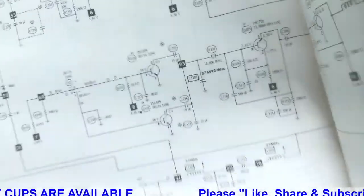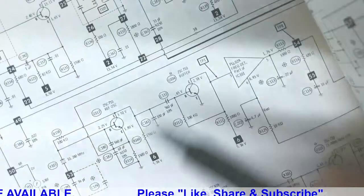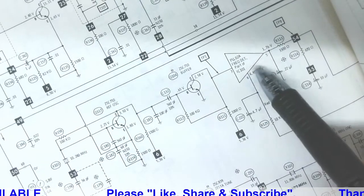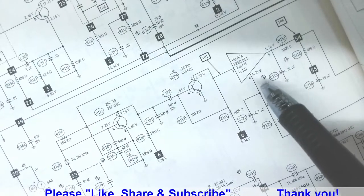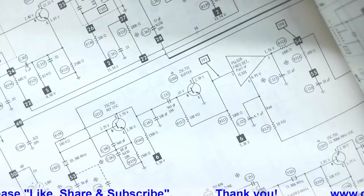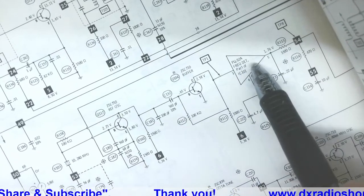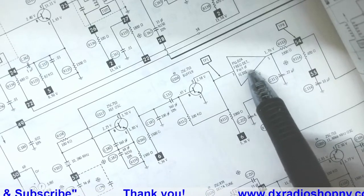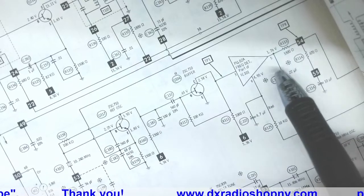And remember, we talk about the chip, right? There you go. Now you see, and this is O2A. That's your PLL O2A, and this is part of IC 101, which means there are different areas that are going to tie into this, which is why you're not seeing all the pins.